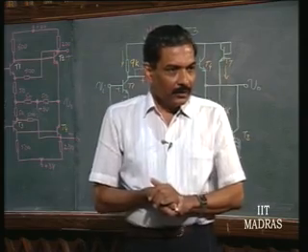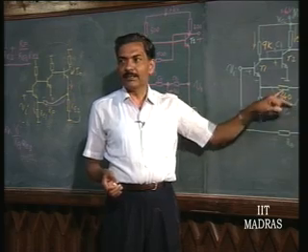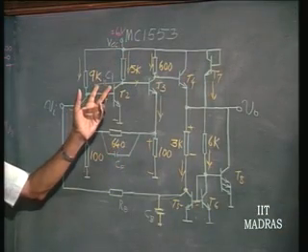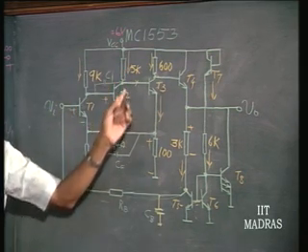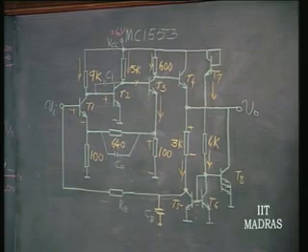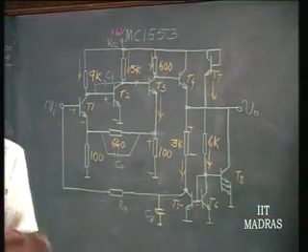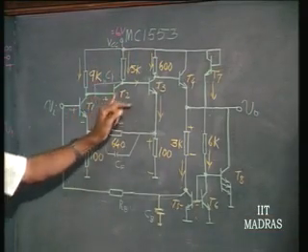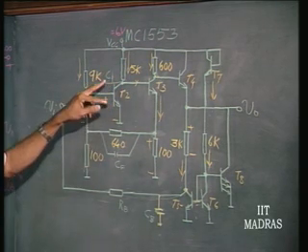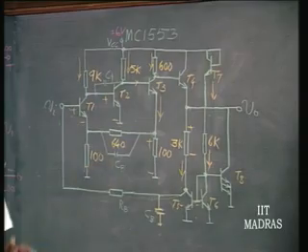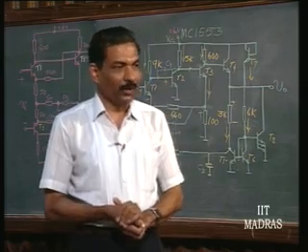Okay. So, as far as frequency compensation is concerned, you can see this lead compensation here coming about, and there is a lag compensation put here. Okay. This is going to be resulting in some kind of dominant pole at this particular point, so that this lead compensation also can work well. Okay. So, we have a dominant pole introduced here by introducing an additional capacitor here. So, again now you have to play with these two capacitors to achieve frequency stability. Now, again you see the amount of uncertainty involved. Okay.